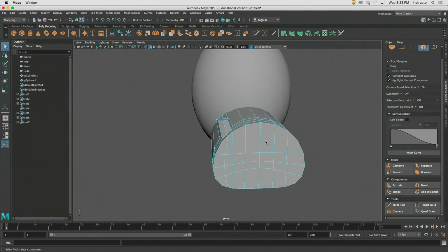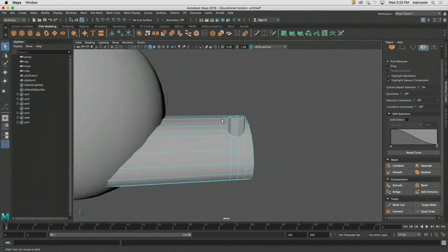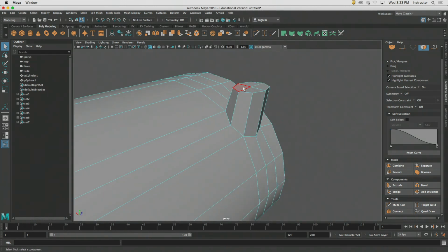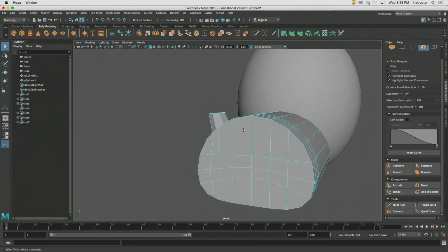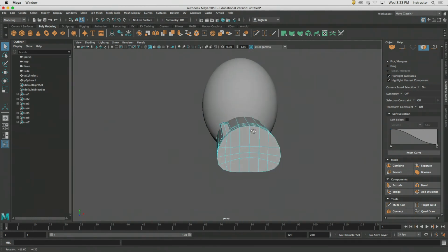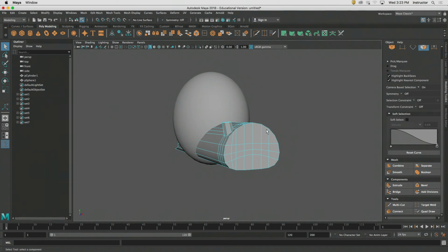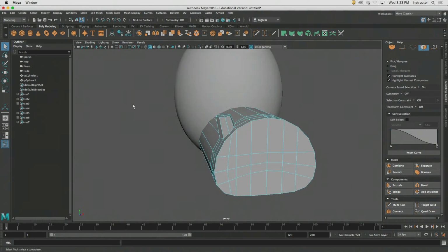Symmetry, okay? Right now, my model is asymmetrical, very much asymmetrical, right? If you look, I got the beginnings of an eyeball over here, okay? And I need another one of those on this side, okay? Mirroring geometry inside of Maya is a little different, okay? And I wanted to bring that to your attention so that you can start to use this as often as you can. It's going to be a central point for us going forward. I want to have the left side be identical to the right side. Right now, the right side is missing a big chunk.